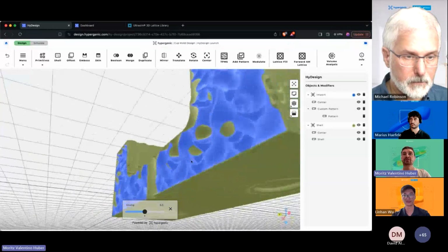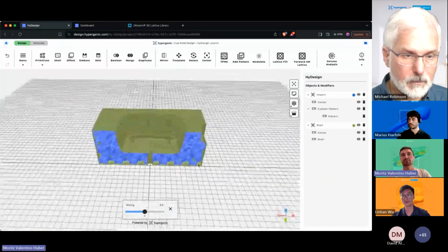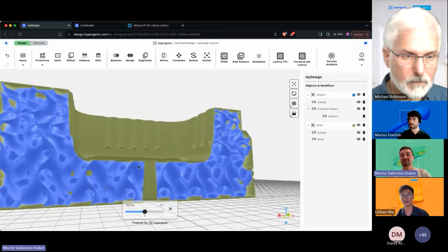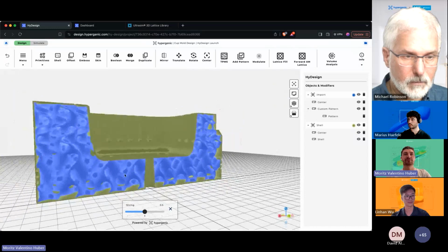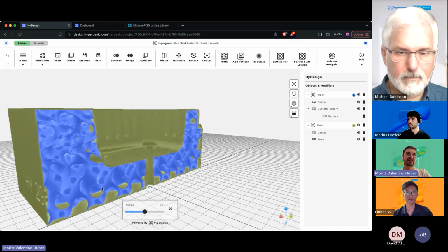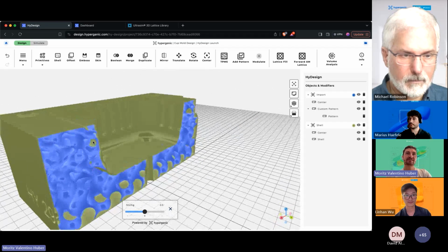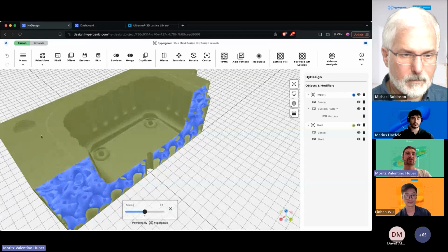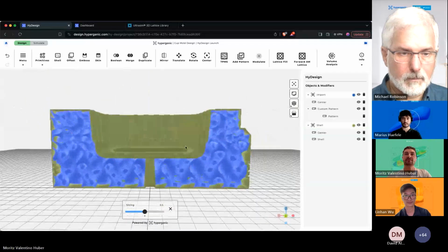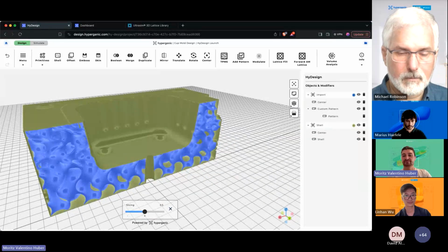Yeah. So here you see it, an infilled mold. Of course, this is not optimized for thermal conduction here. So everybody in the field of molding, please forgive me, it's a demonstrator. But you see the blue is the TPMS infill, in fact, even a merge between gyroid and S surface. And then on top, we have the functional surface completely left intact by applying the shell feature.